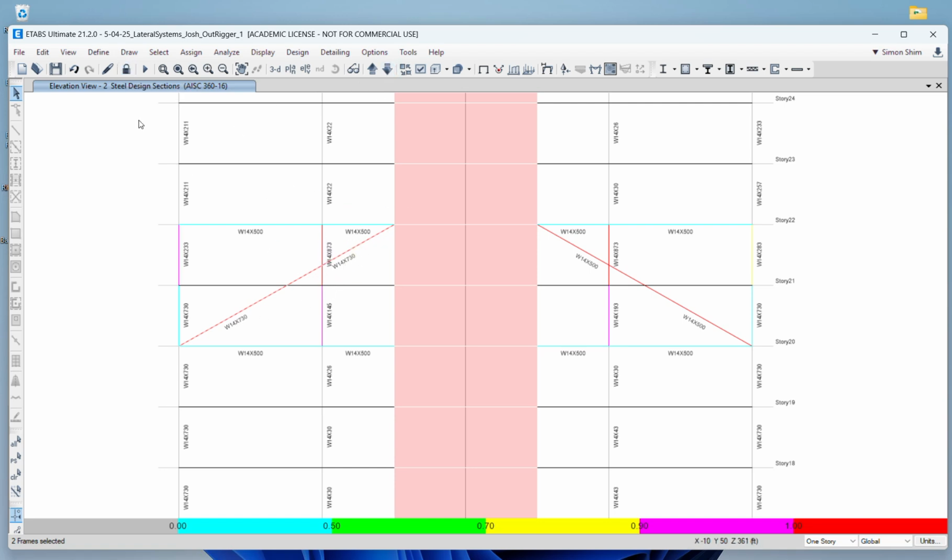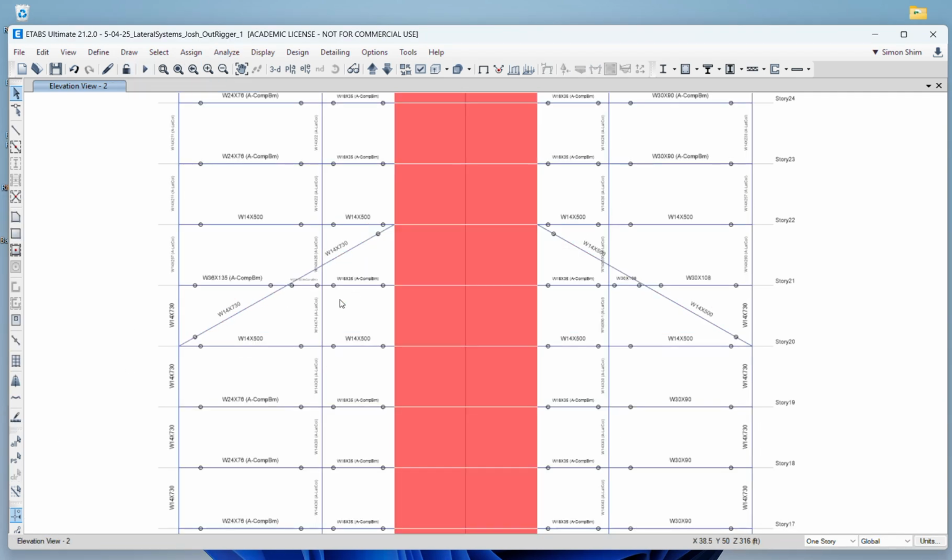Okay, let me just prepare it. Oh boy. Okay, it's this diagonal. Yeah, typically we don't have interior bracing. This diagonal may not be good enough. Instead of this diagonal passing through this column, I think we had better just change the profile of the truss.